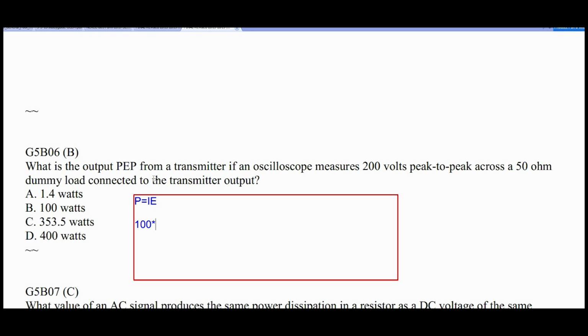So it's going to be times 0.707, which equals, so we've gone from 200 volts to an answer of 70 volts. 70.7, if I type it right. Again, what they're doing is you look at the sine wave, there's a bunch of math involved. You're going to take just as it goes positive, and then you're going to take the root mean square. And that throws me because we're looking for PEP output.